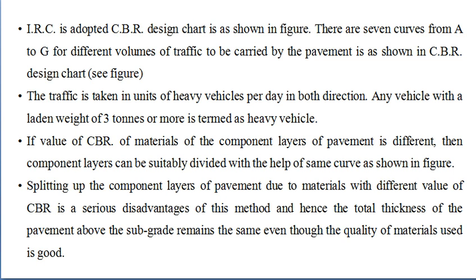Now if the CBR value of the material of the component layers of the pavement is different, then the component layers can be suitably divided with the help of the same curve which is shown in the figure. So splitting up the component layers of the pavement due to the materials with a different value of the CBR is a serious disadvantage of this method, and hence the total thickness of the pavement above the subgrade remains the same even though the quality of the material used is good.